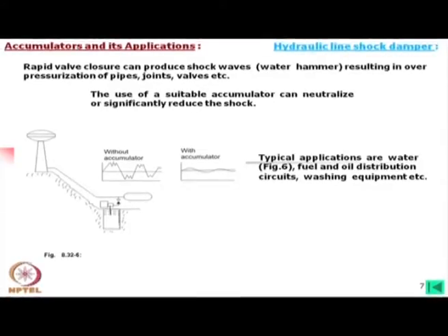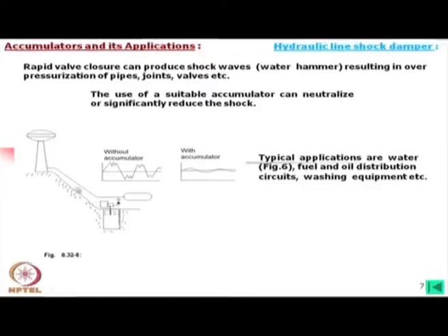In that case, nothing like that is there, oil is going in and giving pressure on the bladder if it is inside, or if gas or air is there, it is just knocking that air or gas, and in that way the shock wave here is reduced. Now, typical applications are water, fuel or oil distribution circuits, washing equipment, etc.